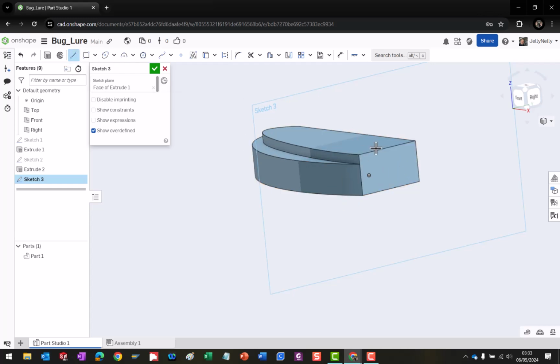I'm going to start the line command, and this time I'm going to use that center constraint. So notice I can snap to the center or the edges of these lines without using the project convert. I used the project convert before because I actually wanted to use those two edges as part of this extruded shape. So I've got this line and this line over here as part of that shape, and then I made the spline here that was attaching to both of those. In this case, I'm just going to use these lines for snap references.